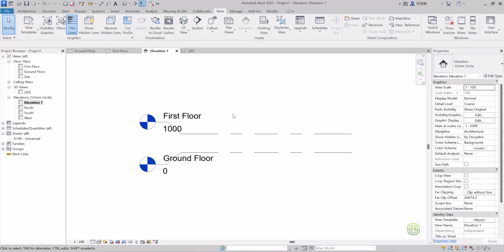If you want to work in millimeters, you first do the unit setup and then start working in millimeters. But if you want to work in meters in AutoCAD, you have to scale the whole thing to meters and then change the unit setup to meters. So you also have to scale all the work from millimeters to meters in AutoCAD.